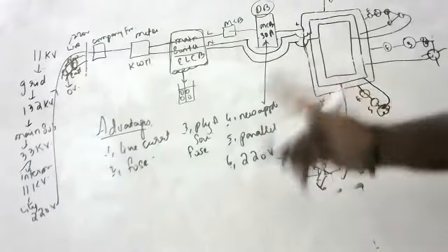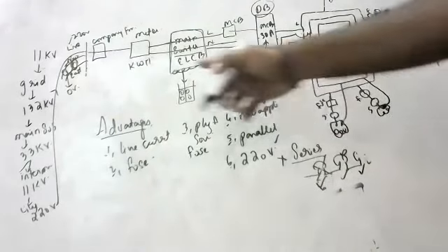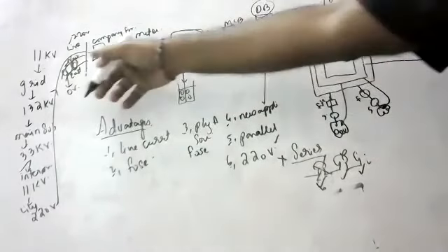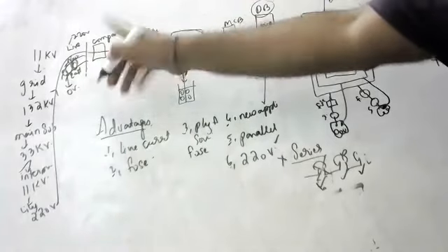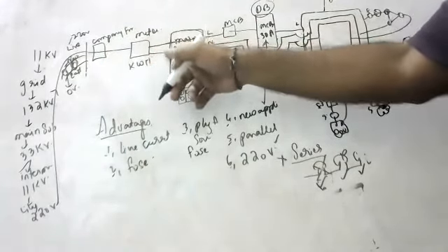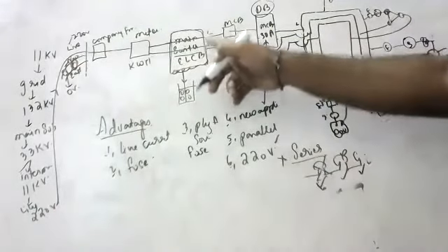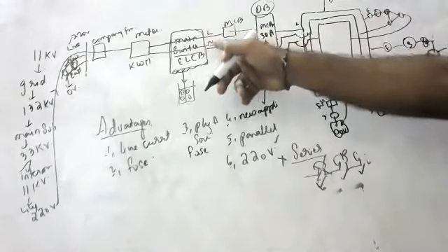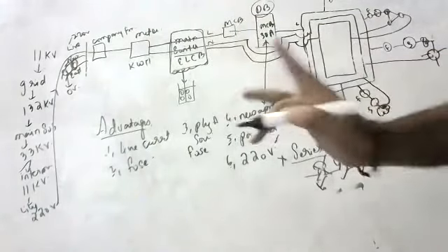Okay, children, so last time I am revising again. Very small. If you understand this, everything is good. See, children, from the pole, the company fuse will be there near the pole or near the house, coming to the meter. From the meter, the live wire and neutral wire both will go through the ELCB. And the live wire will also go through the MCB, but the neutral wire and earth wire will not go through the MCB.